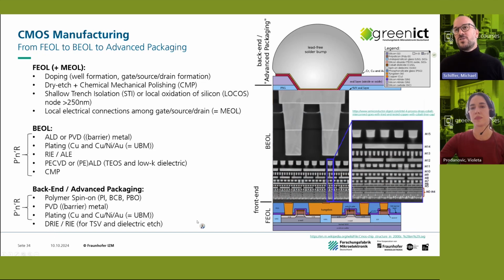Now, a more actual, though also not completely modern, chip looks like this. You have many more metal layers. That means that in the back end of line, process and repeat is getting more and more the focus, because especially there you have etching gases, etc. You also have all the lithography steps. And these two are the main concerns when it comes to environmentally harmful materials.